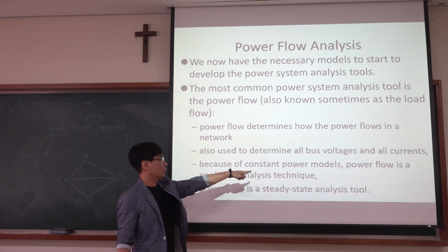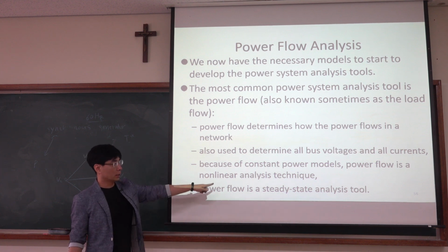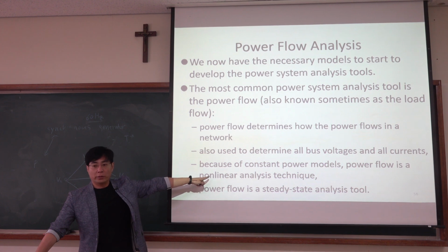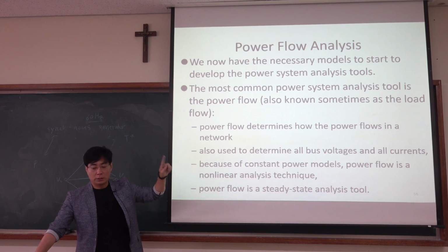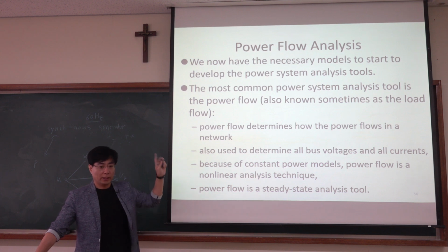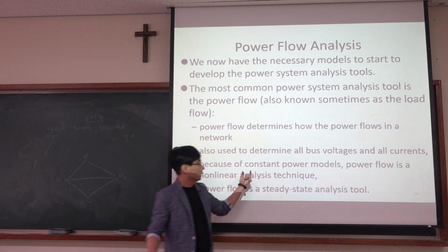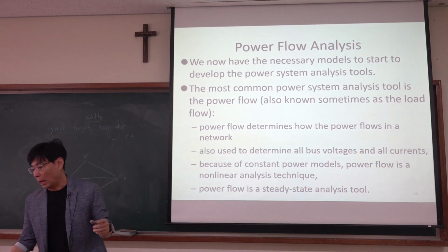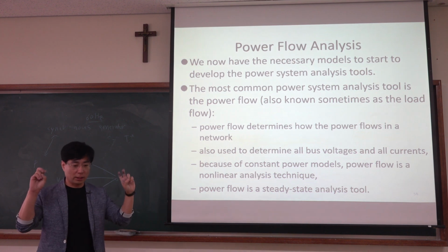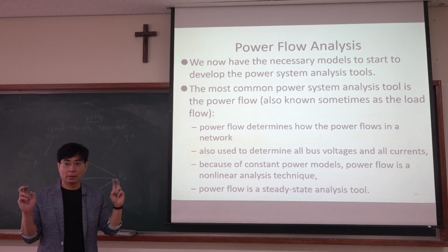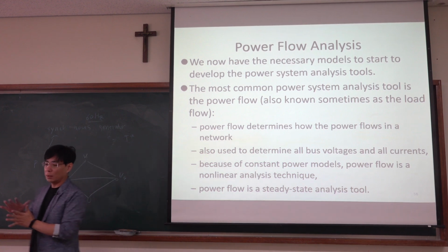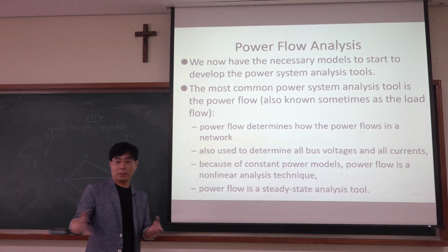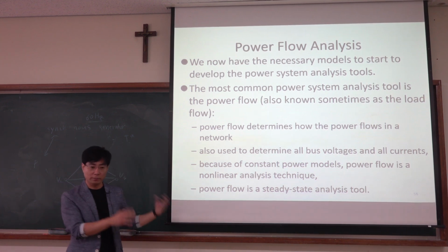And because of constant power models, power flow is a nonlinear analysis technique. So this is an important one. In basic circuit theory, what you learn is just a linear system model. But in power systems, we are using a constant power model at the load side. That means our load requires some constant active power and constant reactive power. And why is that? Because they are using some power electronic devices, like your laptop. Your laptop always consumes constant power, your TV.